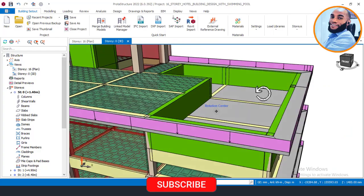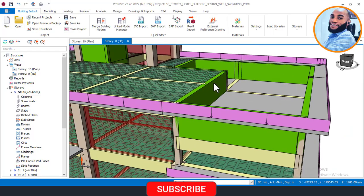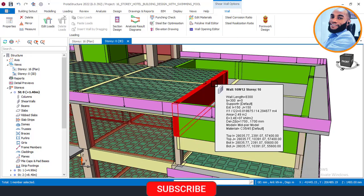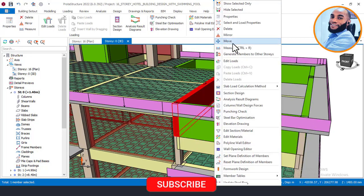To load the walls of your swimming pool, what you have to do is click on one of the walls, then right click, and you will see Edit Loads. So you have to click on Edit Loads. Now if you are using a lower version of ProtaStructure, what you will see is Wall Load. But if you're using this new version, you have to click on Edit Loads.